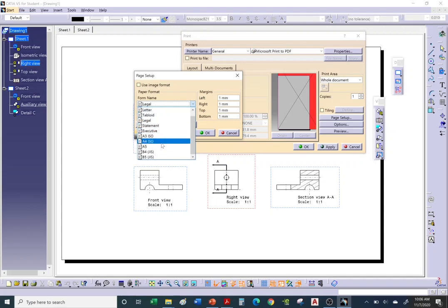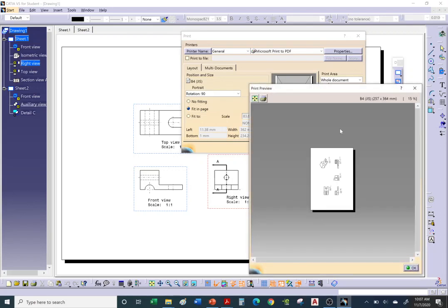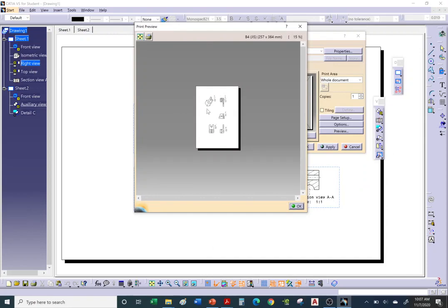If you were connected to a plotter, these large plotters, you would have an A size, B size, C size, D size option. I'll go to B size, Japanese standards. Okay, hopefully that's 11 by 17. Nope, it's still too large. Let's see. Fit into page. That's at 83%. No fitting. All right, so in this case, I would have to say fit into page so I can print. Then I can always hit preview, and it's giving me a preview of what it's going to print.